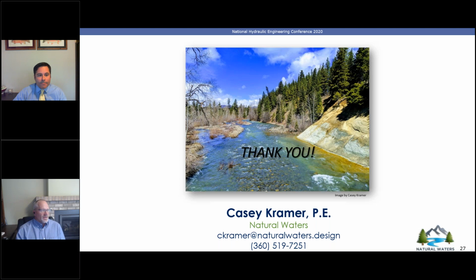I think what it comes down to, and I look at it from a PE perspective, is that if you're doing the work, you're willing to stamp it and say that to the best of my knowledge, this represents site conditions and water surface elevations. So if you're asking the general question, can you stamp a channel throughout the entire reach with no surveyed sections, I would say no, that's not an acceptable approach.